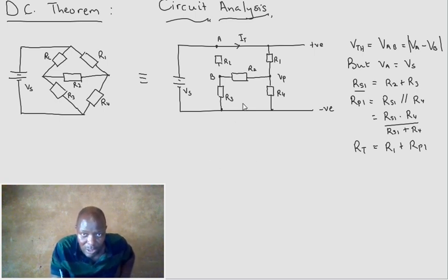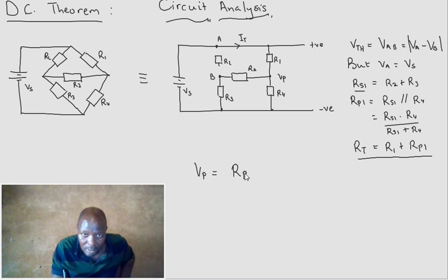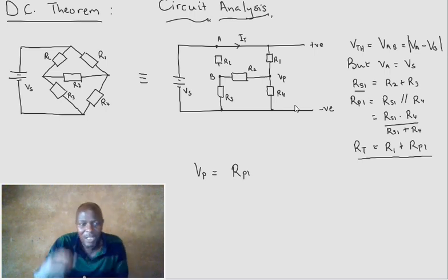I know that R1 plus that is the total resistance there. So if I want the voltage on the parallel network, this would have been much easier than the other method actually. The voltage in the parallel network is simply R parallel 1. We've worked it out, or in this case there's only R parallel, but I always give it 1 in case I later find another parallel network.